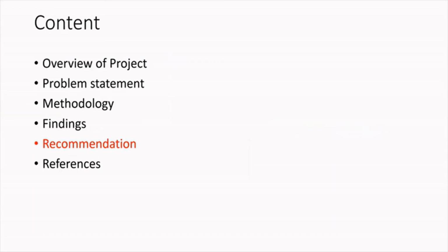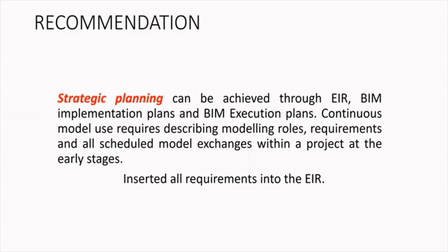Okay, so now what is our recommendation? First recommendation we had was strategic planning. For example, through the EIR, BIM implementation plans or execution plans, model use requirements and rules can all be described and integrated into these plans before the project even starts. And then at a later stage, they can be inserted into the EIR, which is the employer information requirement.